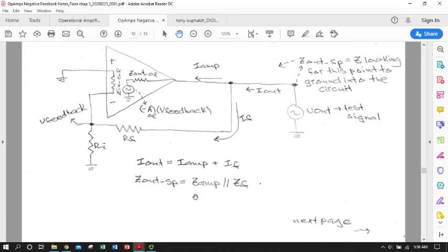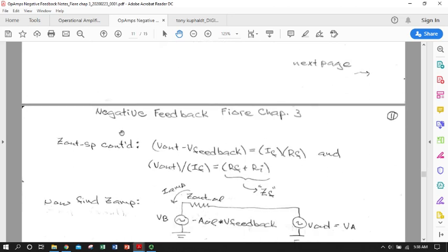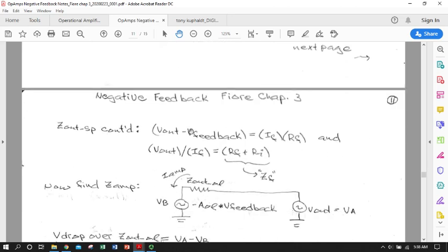The Z amplifier is going to take us a couple of steps to derive, but it's not really that hard, because it's just a couple of things in series that we relate to other things we've already derived. ZF, which is our effective impedance of our two feedback resistors, that's really easy. They're just in series with each other. So we'll do a little bit of algebraic wrangling here, starting with our feedback network.